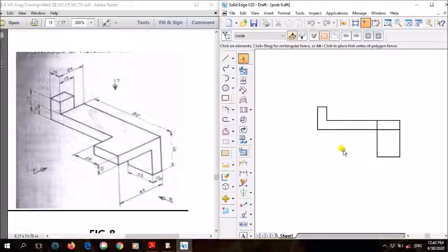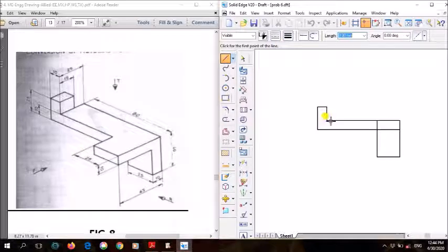So there is another section that is not visible that we need to draw. So you can see here, this is the solid whole part, right? So whatever this projection is there, only up to here it is 15 mm. So whatever this 10 mm is there is no projection, it is blank. So whatever this leftover part is there, that solid part. So when you see from the front view, whatever this edge is there, you have an edge at that side. There is an edge here, so that edge is not visible. So that edge we need to draw here using dotted line. Clear? So here again, using thick dotted line, what you can do is start from here and end it here. So like this, you need to show a dotted line. Clear? So this is the front view.